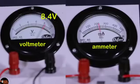I think it's probably because the voltage supply is a bit faulty. It's giving us a voltage higher than 8 volts, maybe around 9 volts. That's why the potential difference across the wire is 8.4 volts. But we are interested only in the potential difference across the wire. So for our experiment, it doesn't matter.